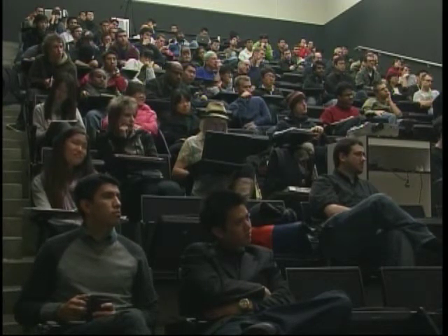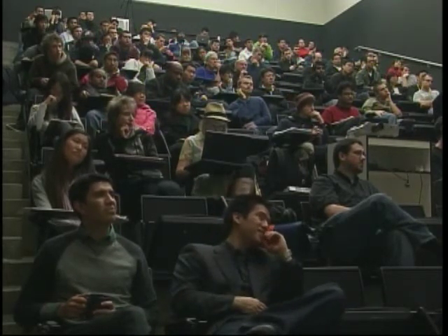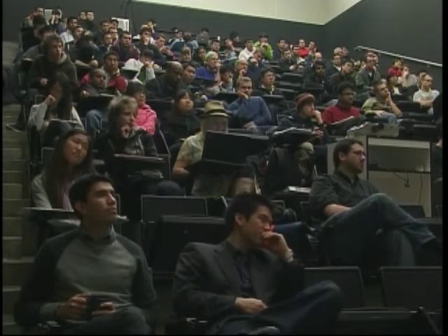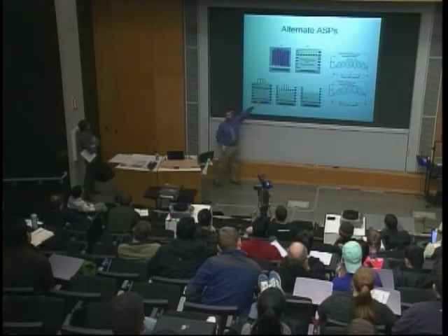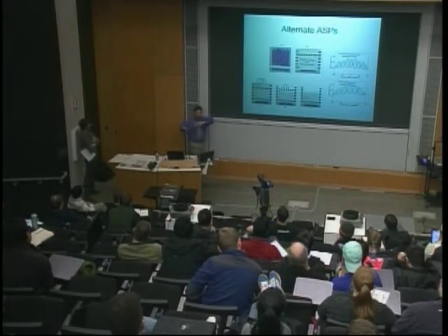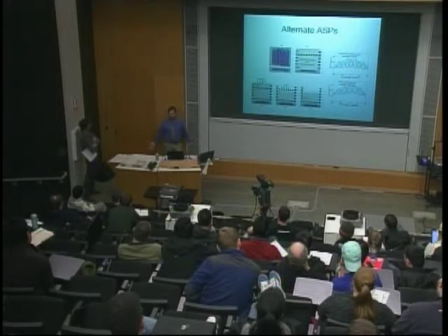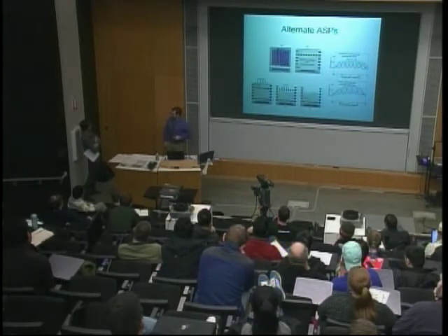We just showed that you can build alternate structures that use what are called phase gratings, using a little bit of tricks out of MEMS, where you can basically remove the top grating and replace it with a crenellated sort of oxide surface. Then all that light's kept, but you get the same effect. And you can build an alternate set of detectors using finer grained photodiodes and remove the second grating. So we actually have a forward device path as well, where we can eliminate our light loss problems but still keep all the functionality. That's my little plug.